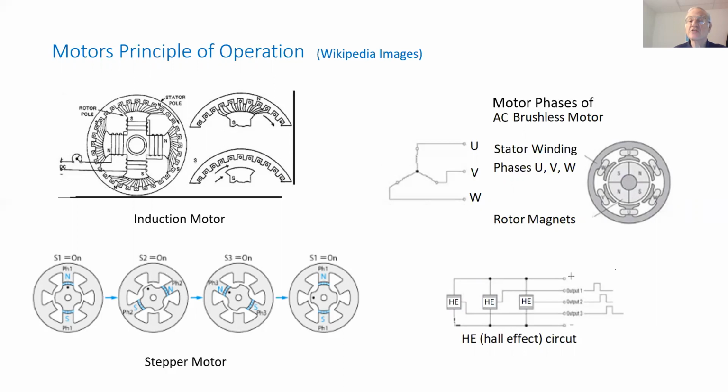And we see the phases over here, and switching, as we'll see later, will drive them. The way to switch the electrical logic circuit is by pulses which come in from Hall effects. Hall effects will generate a signal when the magnetic flux of the magnets on a rotor passes through them.